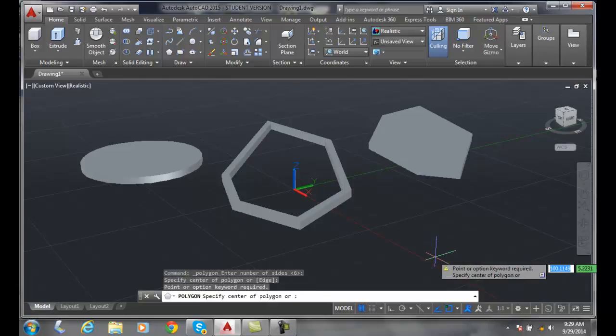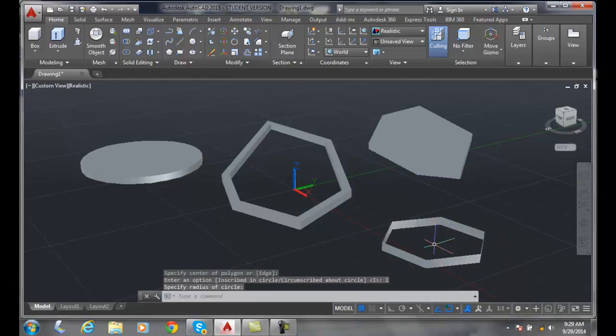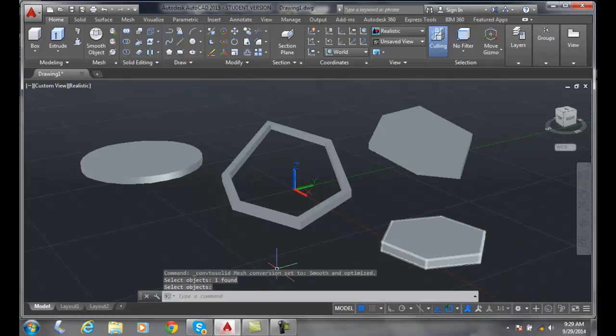And we can actually do a polygon, like a 6-sided polygon, for example, and it's still got that thickness command, and I want to convert it to a solid. Now, before I leave and quit doing that, I need to set my thickness back to 0. Otherwise, every 2D object and 3D object will be set to that 4 unit value.